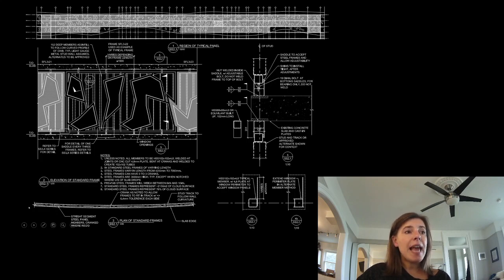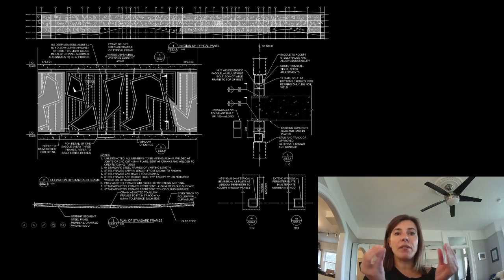Here is the edge drawing showing the intent of how the track needs to fit relative to the concrete slab. And I actually modeled this in 2D as well. Once I had the rolled out scope worked out, this was somewhat easy to go back and forth. I drew all of this in elevation, and I drew in plan in 2D the edge of the concrete to show how I could fit my track and make all of these straight line segments hit within it or not exceed that. I showed intent for how we could build in tolerance.